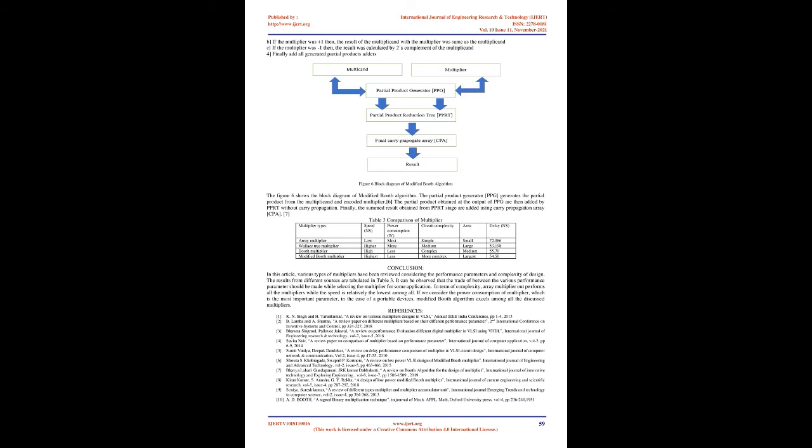In a given multiplier, a group of 3 bits is considered. It initiates from the LSB and the first group is formed by 2 bits. Onward, consider a group of 3 bits in which 1 bit will be overlapped with the previous group, as shown in figure 4. Thus, each group of the multiplier will result in the production of one of these 5 values: -2, -1, 0, +1, and +2, which are tabulated in Table 3. Consider the scheme of the radix 4 Booth multiplier.